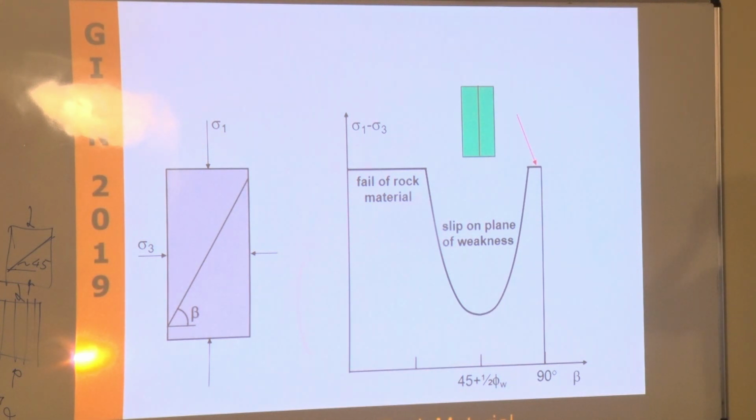So when you are dealing with rock, especially sedimentary rocks like shale, gas shale, really big unconventional oil and gas are all in bedded rock. You really need to account for the presence of these bedding planes and their orientation with respect to your loading when you are going to engineer them. Another aspect of rock mechanics that is very important, and was mentioned before, is the nuclear waste industry.